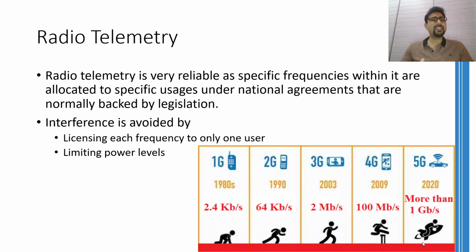However, by increasing the frequency, the range the signal can travel in the medium will decrease. Using a high frequency requires fast modulators and demodulators so that they can work with a rapidly varying signal. Therefore, in the 1990s, in the era of 2G, we would not have seen so many antennas or mobile communication towers in our cities.